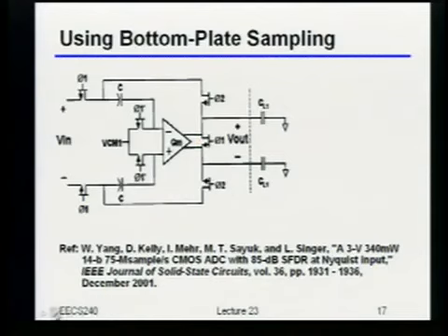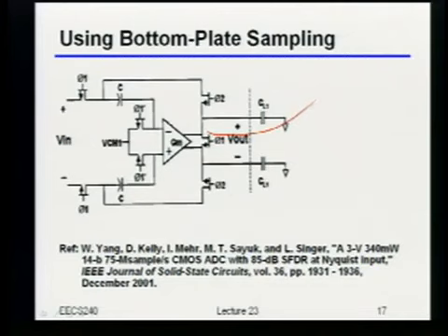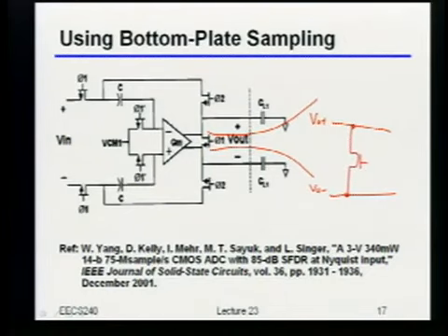Okay? So if you think a little bit carefully about that, the way you're going to want to build this looks something like the following. Let's say this is VO plus and VO minus. If you take that switch and tie it up like this, let's say that's the source and that's the drain. Remember, all the implants and everything are slightly directional, right? So if there's any asymmetry inside of that switch, some charge may split unequally, okay?